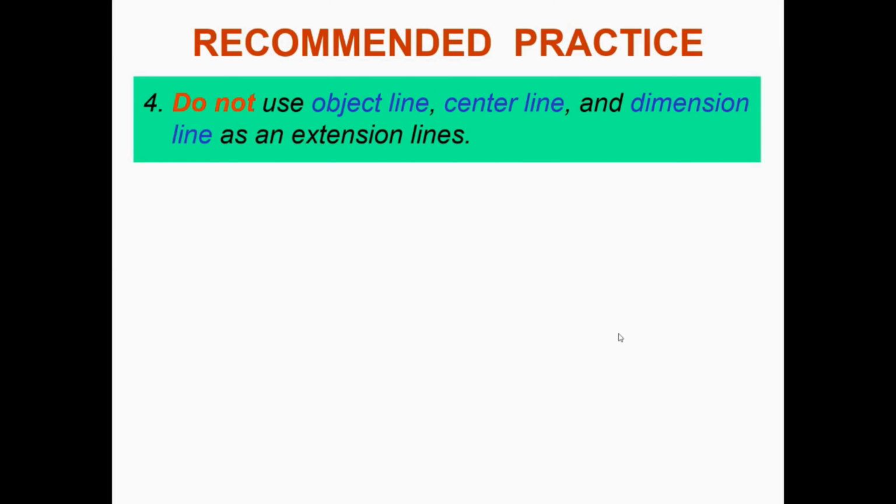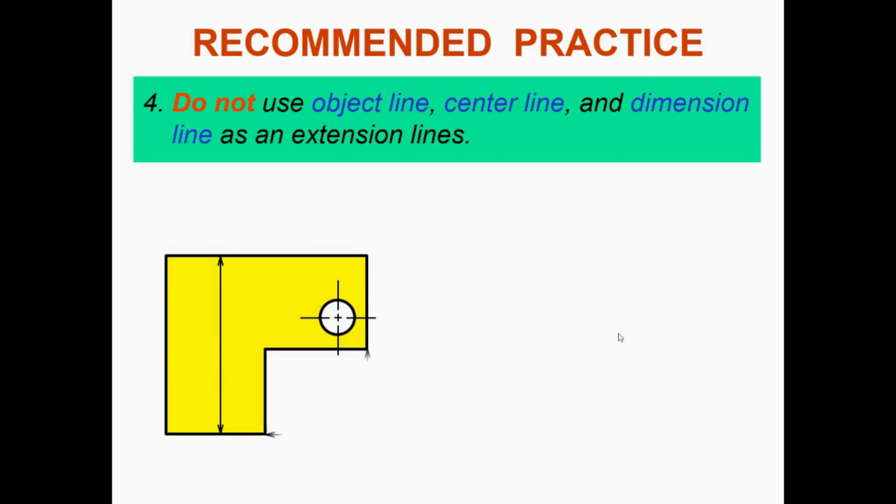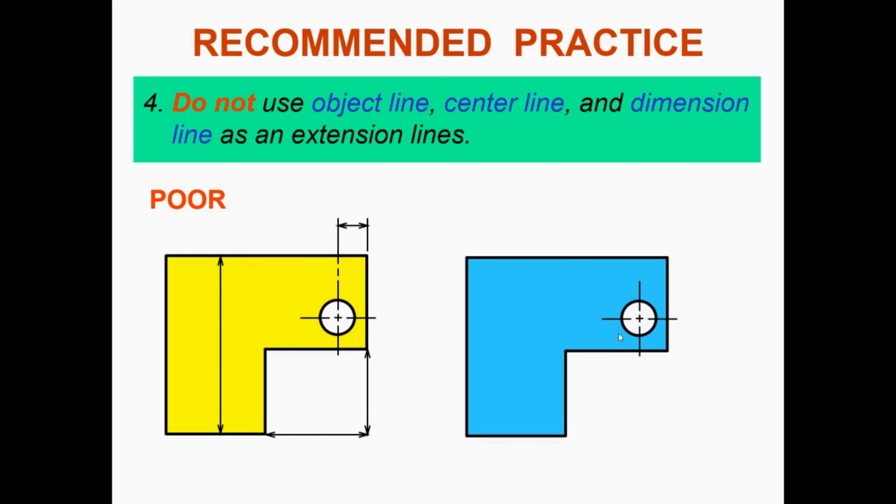Do not use object line, center line, and dimension line as extension line. This is very, very important. You're not supposed to use the object line, center line, and dimension line as an extension. The ones you see here, this is a very poor presentation, and this is the right presentation to go.